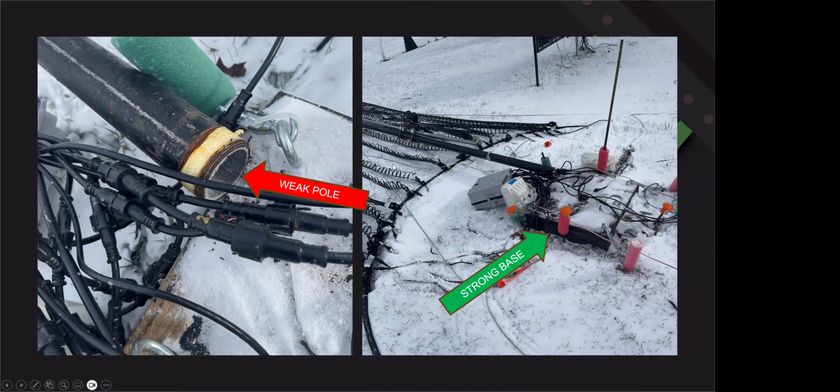Something that was pretty popular several years ago, I think people are getting away from it, was using threaded pipe to go into here and then going into a matching threaded connection going into a portable base. Threaded pipe really is not designed for bending whatsoever. The threads damage it. You start getting rust in there because usually it's not covered. They tried to prevent some of this, but not all of it. You can see where it corroded, and it just broke right along there from the looks of things.